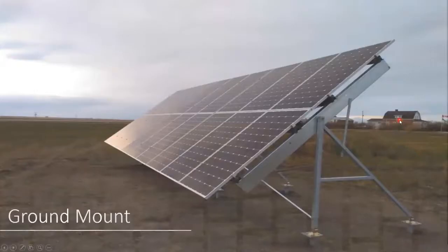The last option we'll talk about, and if you have the space, it's a great option. Typically more costly to install than a sloped roof mount because you're getting into footings, helical piles, screw piles, or slab. But from a production and efficiency standpoint, ground mounts are the best because I can pick my angle, I can pick my orientation, and I can even go up from there. So a fixed angle ground mount would be the most simplistic. What you're looking at here is what's called a seasonally adjustable. So I can adjust multiple times throughout the year, summer solstice, winter solstice, as that sun angle changes.